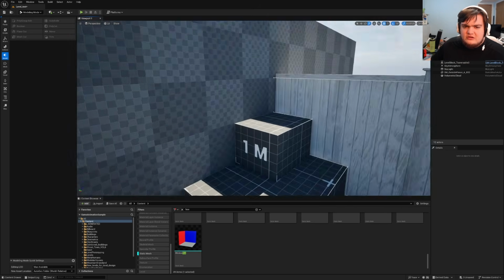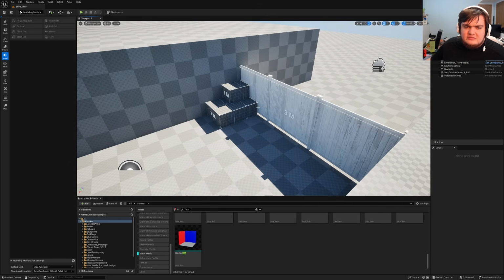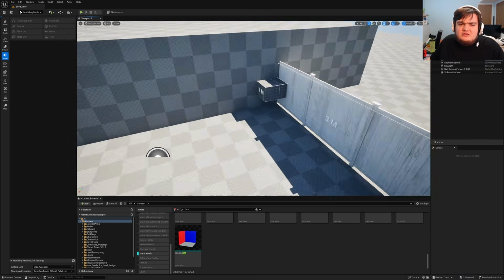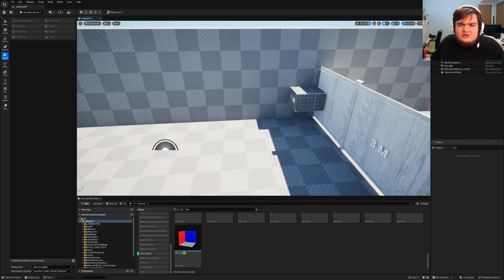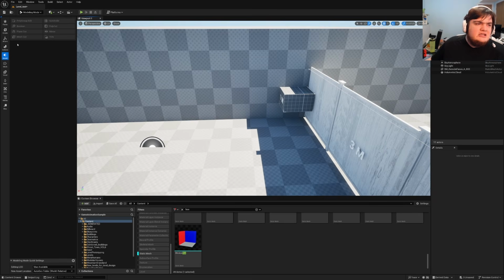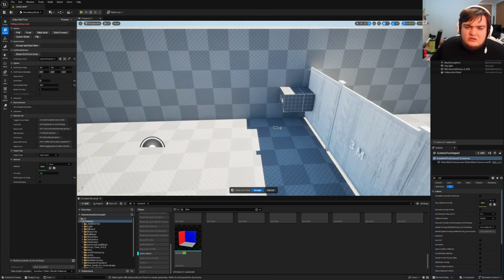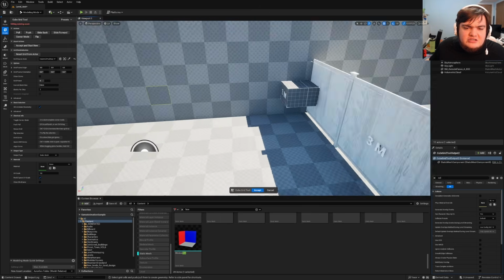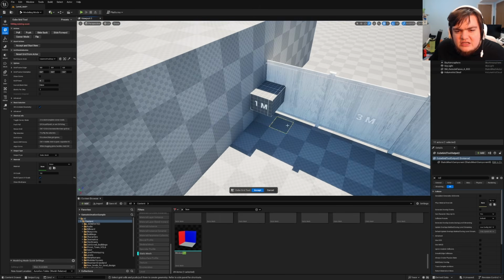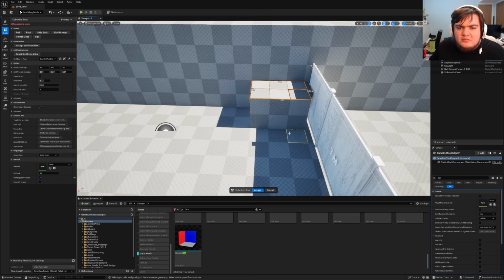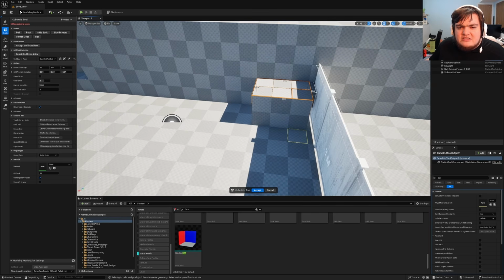But what if I don't want to go across this way? What if I don't want them to traverse over? So what I'm going to do is keep the little traversable block here so I know exactly how high 1 meter is. We're going to go into create, click the cube grid, go to cube grid. We're going to reset the size to what it originally was. We're going to go over here, scale up, up. There we go. Now we know what our scale is supposed to be.